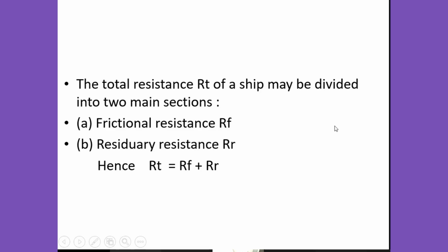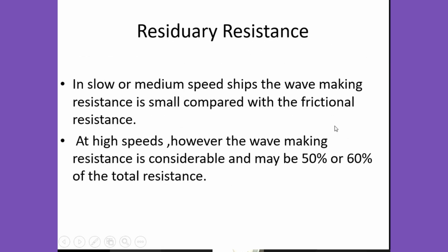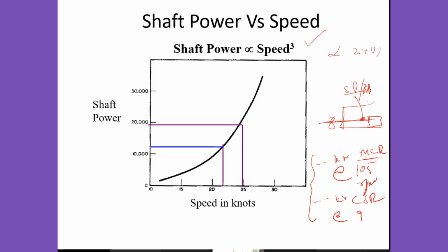And it has been experienced practically, if the vessel remains at anchorage for a long time, or operates more often in tropical waters, and has longer port stays, those types of vessels will have more sea growth, and therefore eventually a stage may come where it will become very uneconomical.